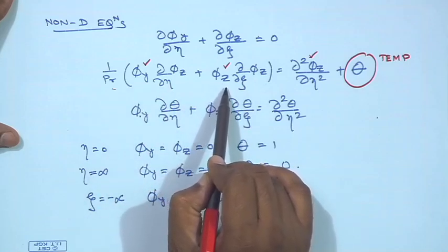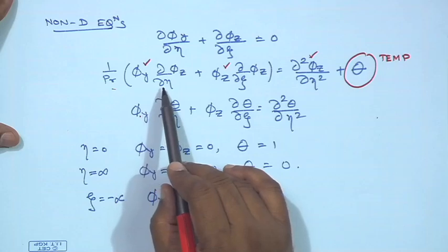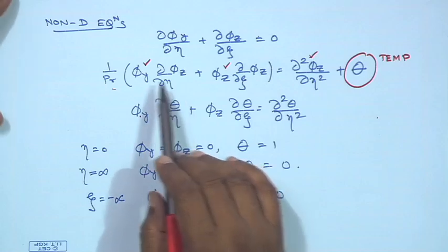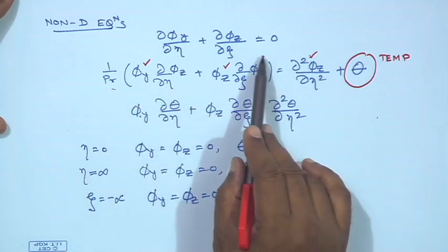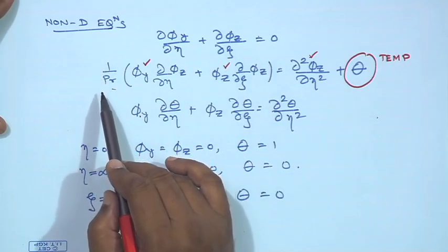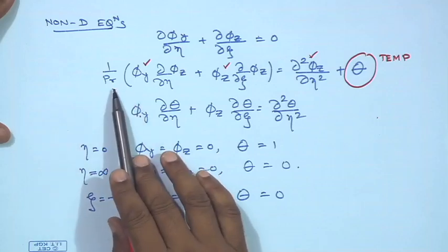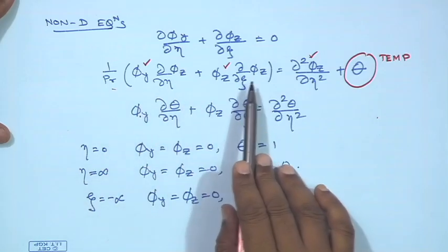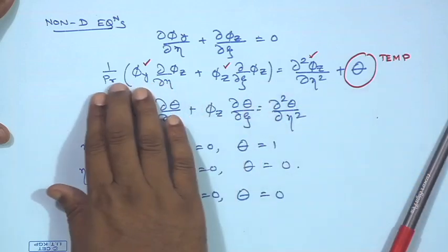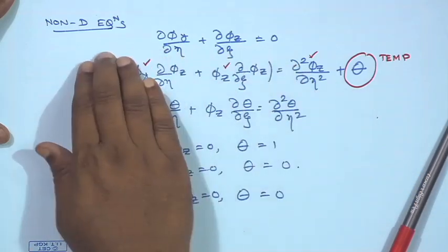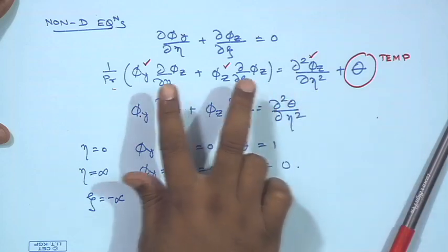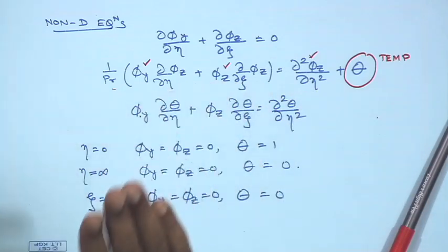In the limiting case, when you have creeping flow, you remember we have studied creeping flow before. So, if we have creeping flow, then this entire left hand side can be made equal to 0. But here the problem may not be equal to creeping flow, but it is still a slow flow. So, the effect of the left hand side of the Navier-Stokes equation on the final form of the solution should be significantly smaller.